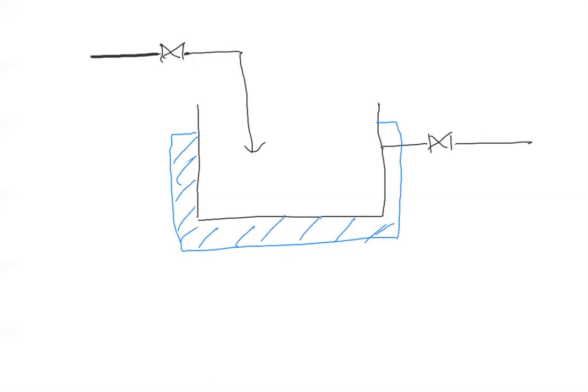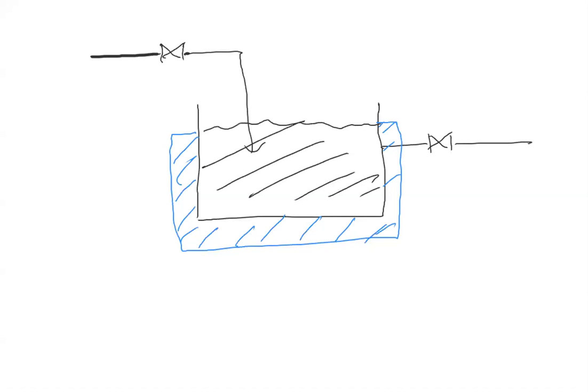Air only, because these are pneumatic operated valves. Suppose the valves are very big. In the plants, if you see, some valves are extremely big, then air cannot operate those valves. Then a motor will operate the valves. They are motor driven valves. But for the rest, mostly it is air operated valves only.